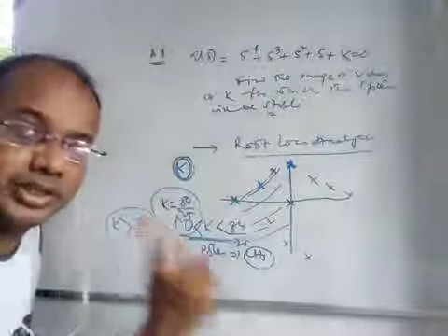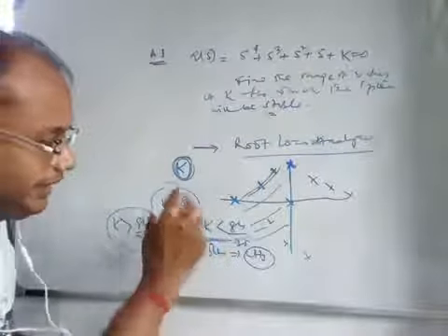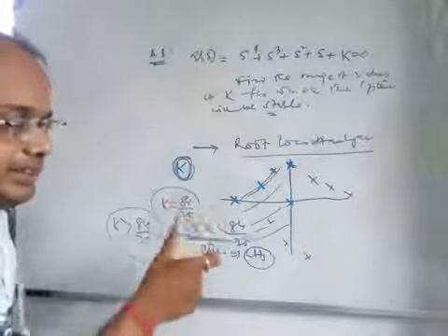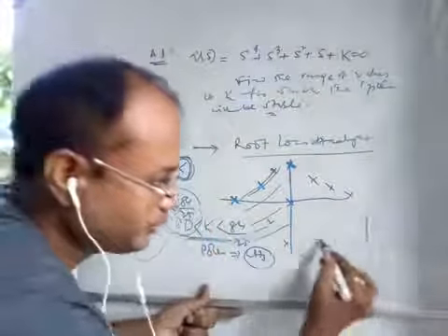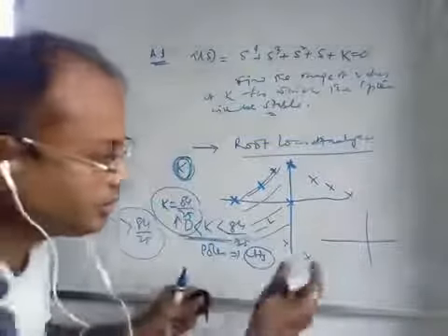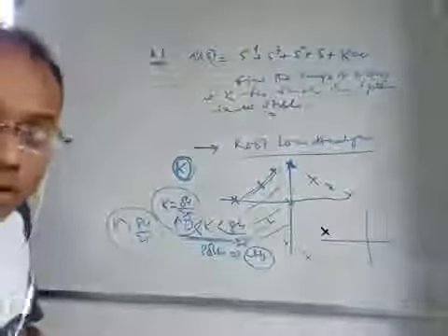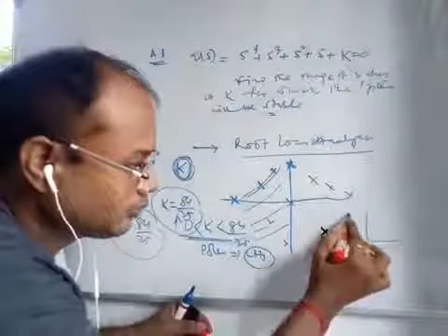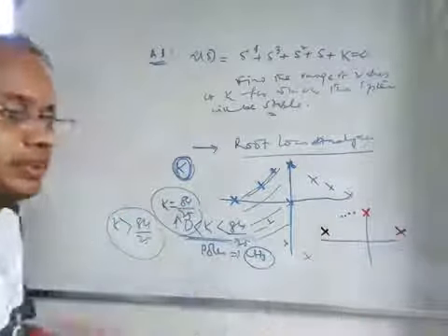That means the system pole reaches the right half of the S plane. So from the basic concept of the Routh array, if the gain is varied by a certain amount, the system pole may move from the left half of the S plane to the imaginary axis to the right half of the S plane.